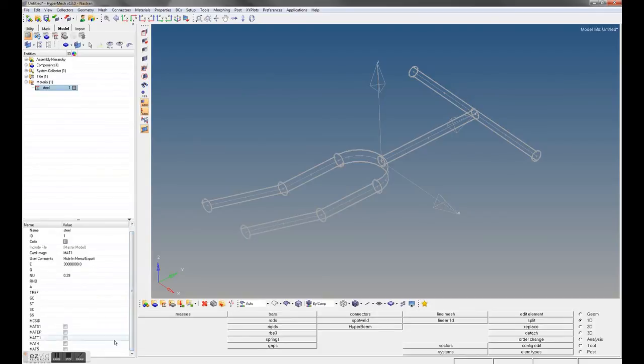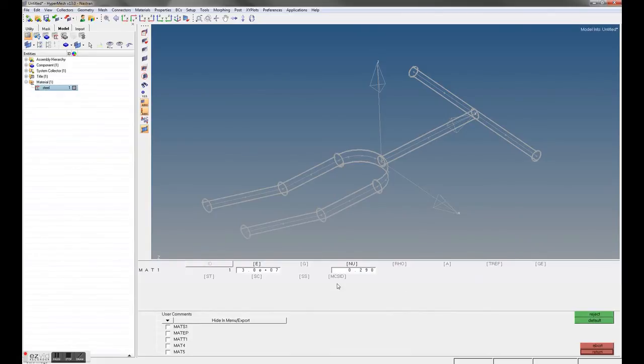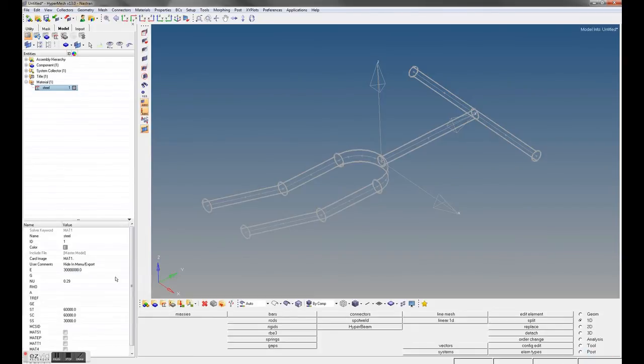These are all the fields. You can see here that these fields do pretty much correspond to the Nastran input stuff. If you want to see it in more of the Nastran format, you can right-click on the steel card up here in the Entities menu and select Card Edit, and here you go. So if you wanted to add in the tensile strengths or the tensile design conditions, the compressive ones, and even the shear ones, which I guess would be about half of that, right? You can do that or not. It's up to you, right? But you can edit the cards directly in there.